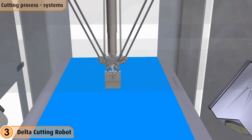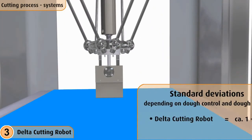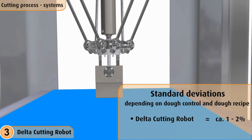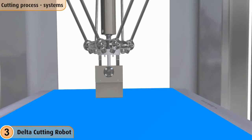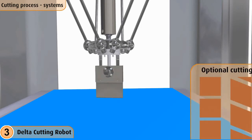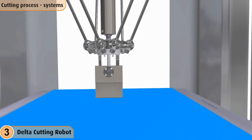The cutting tool separates the dough strand exactly, according to weight specifications with a standard deviation of only 1 to 2%. The cutting tool at the end of the robot arm can be turned within a plane by 185 degrees or 360 degrees, respectively, so that the robot can also cut triangles and diamond shapes out of the dough belt. These products also have a weight precision of 1 to 2%.